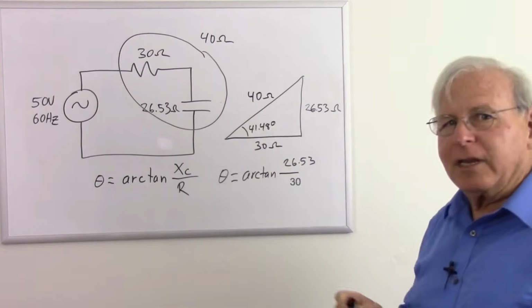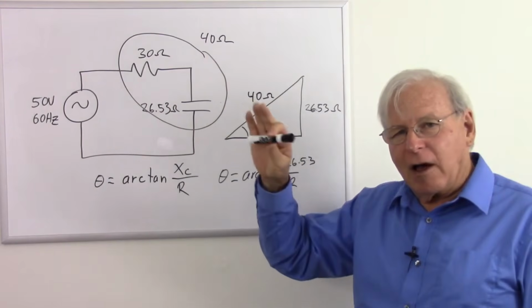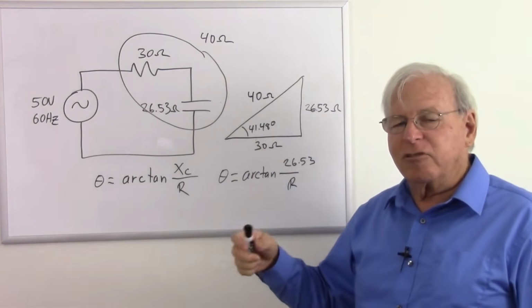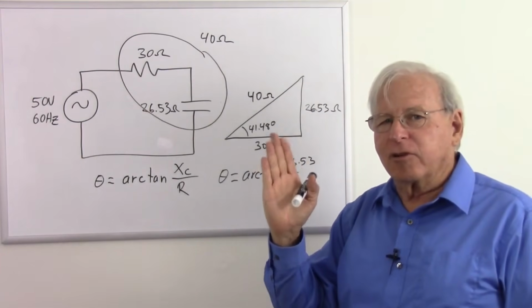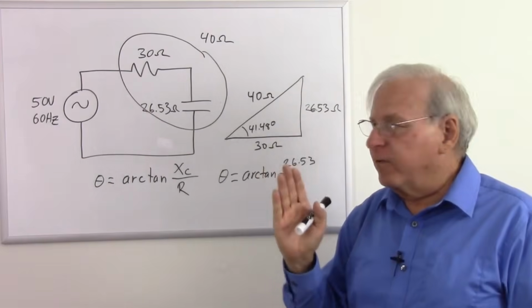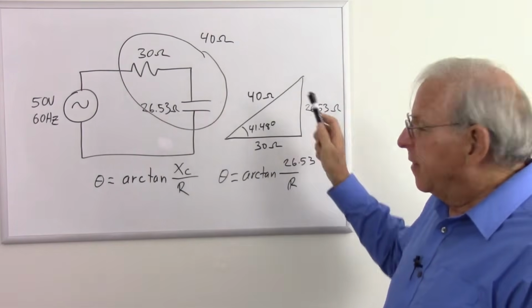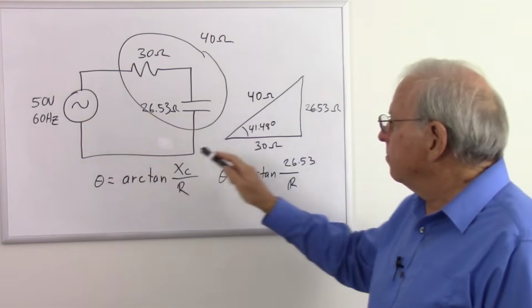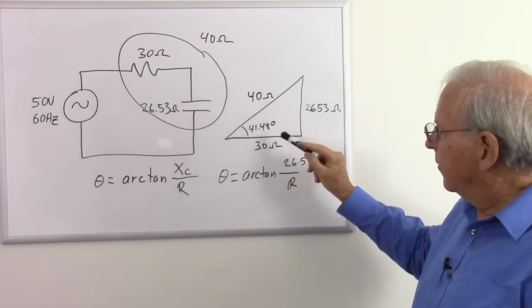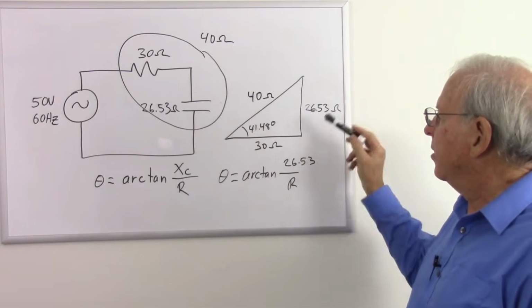And so remember when we did all those gyrations and figured out how all those sine waves lined up with each other just because of how that circuit works. If we freeze time and see that the circuit acts like a DC circuit, we found that our current was leading the source voltage by 41 degrees approximately. Well, there we go, 41.48 degrees.